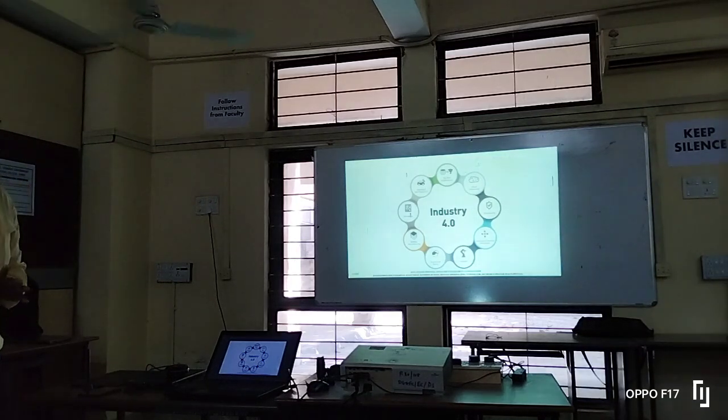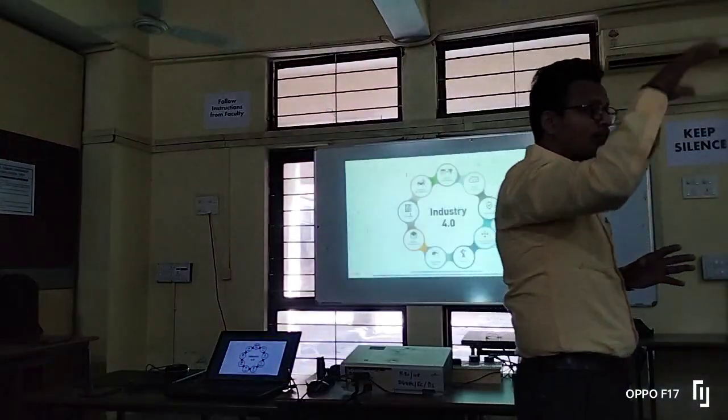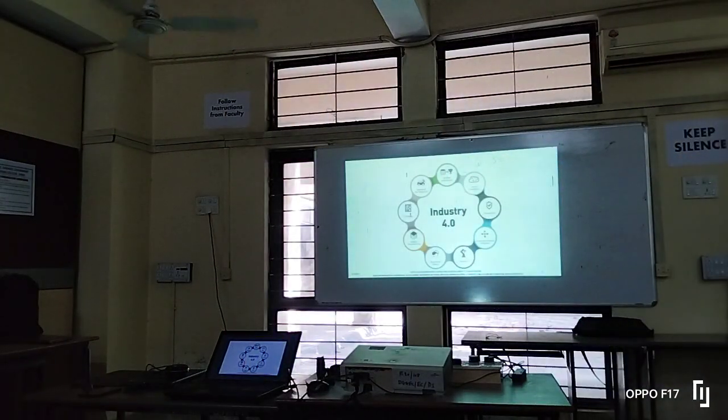Okay, so in the same way, a hierarchy is there in industries. One supervisory PLC is there, and under it are slave PLCs, master and slave PLCs. Under any slave PLC again there can be a more complex network. Some PLCs are there or devices are directly connected. That's called vertical integration.